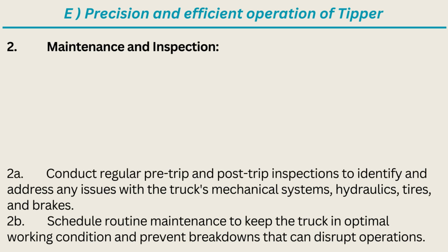2. Maintenance and inspection. 2A. Conduct regular pre-trip and post-trip inspections to identify and address any issues with the truck's mechanical systems, hydraulics, tires, and brakes. 2B. Schedule routine maintenance to keep the truck in optimal working condition and prevent breakdowns that can disrupt operations.